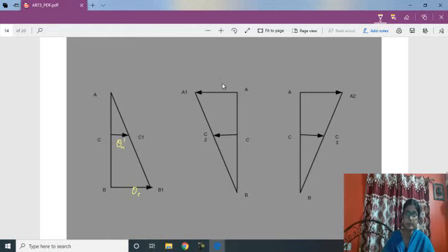So this movement of point A to A1 may be labeled as say theta F due to feedback signal, and as a result the C will move to new position, say C2, and this is the flapper movement away from the nozzle direction, say theta n 2 dash.